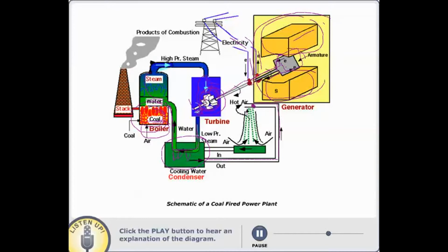The purpose of this cooling tower is to cool the water that is condensing the steam. It is simply like a shower head: hundreds and thousands of shower heads at the top of an almost 10-story tall building. When these droplets fall down, the air going around these small droplets picks up the energy from them, and hot air goes out and cold water comes down.